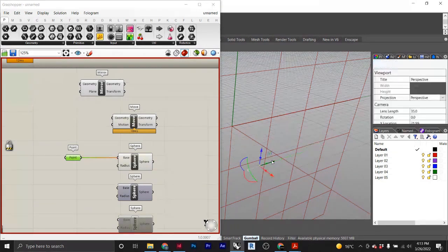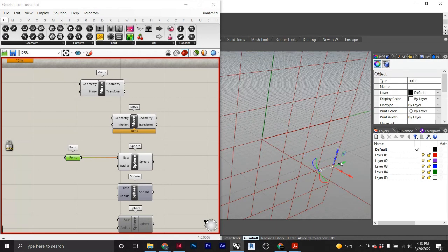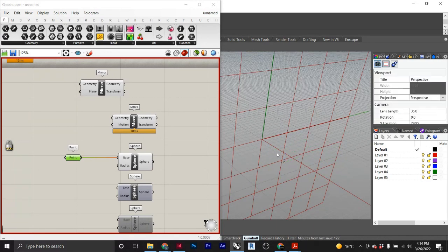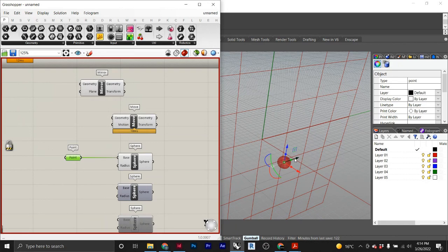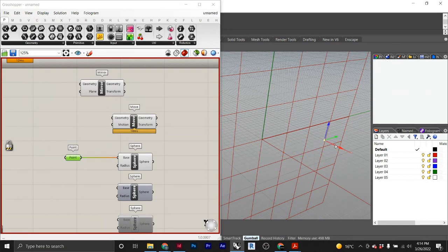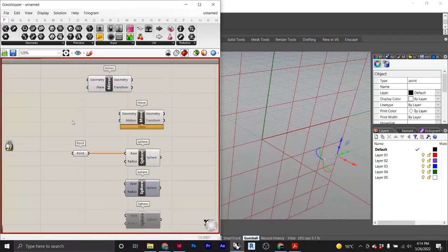Now, this allows you to make changes to things. You'll see the preview has gone, but my script is not actually running. So I can go and change something, and when I'm ready, I can run the script again by simply unlocking the canvas, and the script will run again. The play button does one more thing. Let's say I put the lock on. You'll see the preview has gone because Grasshopper is kind of asleep at this point.